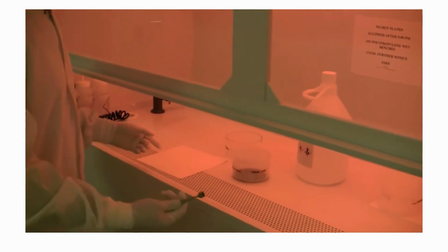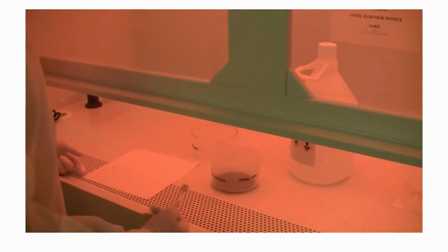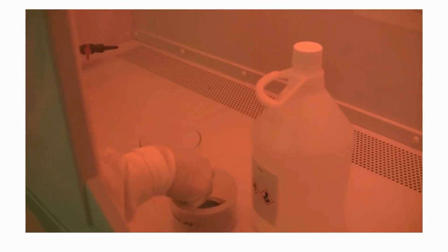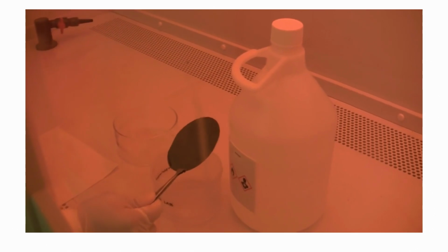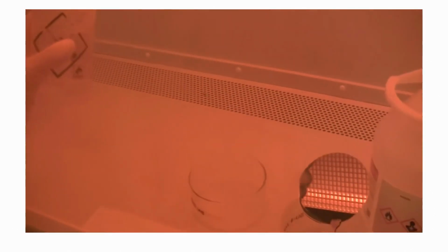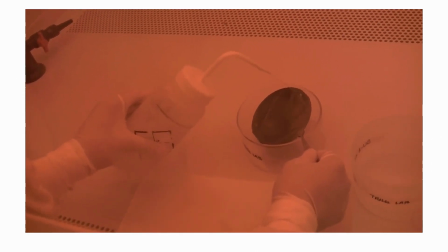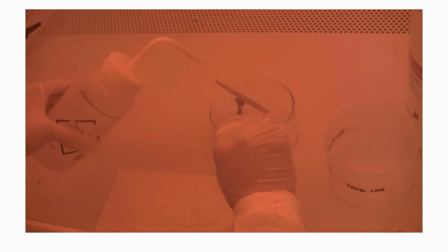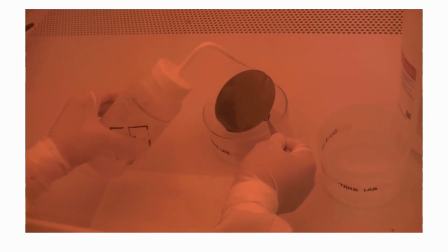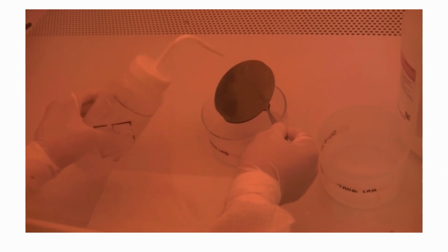The last step in SU8 development is to check whether or not it's actually developed. So when you think the time has gone by, you can take out your sample with your tongs. Make sure it doesn't drip out. And use isopropanol, which is the yellow one here, labeled isopropanol. And you spray your wafer. You do it very slowly and gently. You don't have to splatter it. Just kind of take your time. Just slowly get both sides. Just make sure it's thorough and just take your time. Notice I'm using a separate container to catch this. You don't want to mix the developer, and I'll explain why in a second.